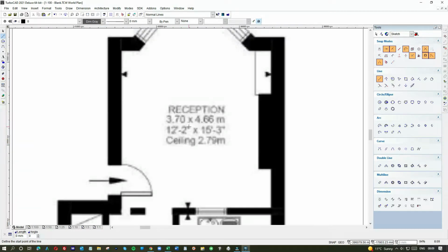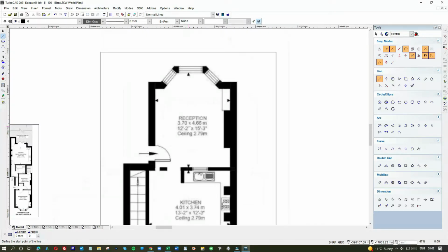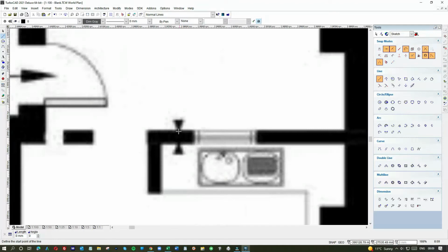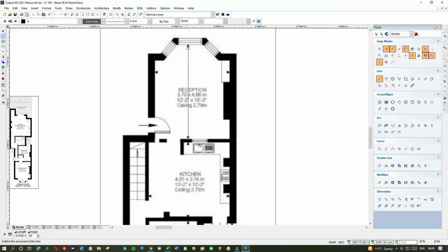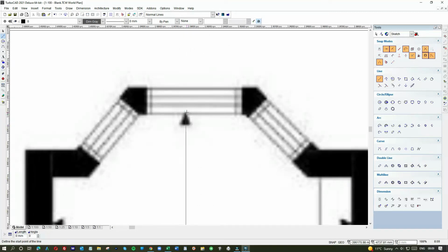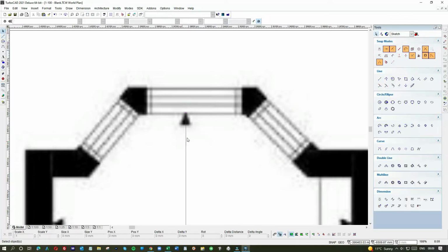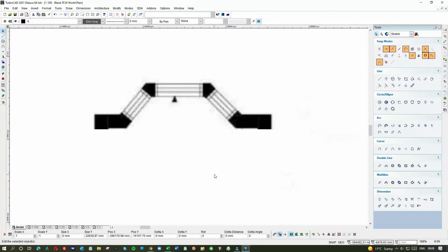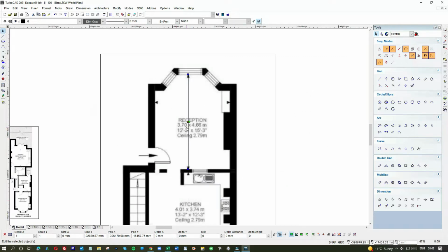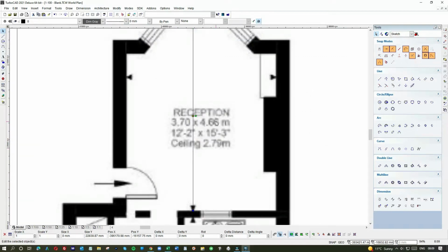So again, this one is sized, so it's going to make it easier. Do you remember the routine now? We go to the line tool and we draw a line from an area where we know what the measurement should be. Let's have a look at what the line size is, by looking at the property inspector at the bottom. It says 22839. So what should it be? It should be 4660. So it's miles out.